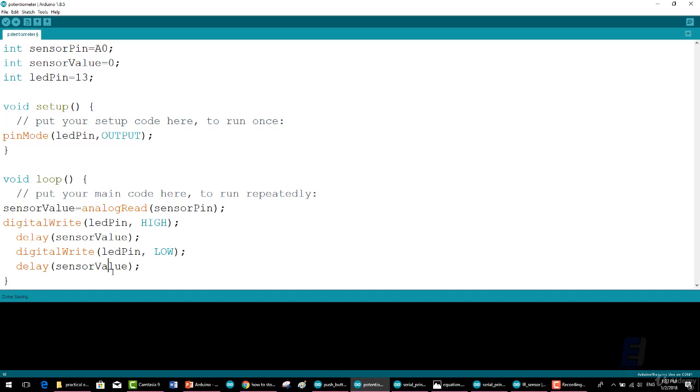Once the potentiometer is connected, upload this sketch to the board and change to the serial monitor. As you rotate the knob or slide the slider, the value should change between 0 and 1023. Correspondingly, the LED will blink with a faster or slower delay. You can now read the values and use them with your code. The new function used here is analogRead, where the pin selected is pin number 0. If you used analog pin number 5, you should change the code to read int sensorPin = 5.